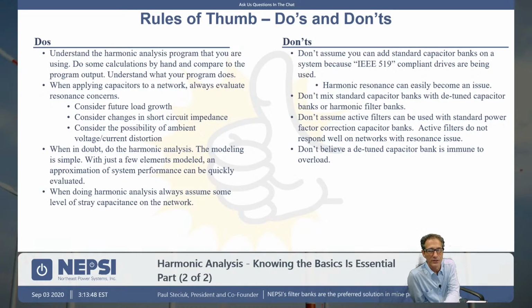Because that will teach you how to get around and how to analyze: what are the ohms, what's the current flow, is it in amps, is it in percent, is it VTHD, what is that value? It really pays to spend the time to dissect the program that you're using and really understand what the output is and what you're reading. You should be able to replicate it on paper, and once you can do that, you will definitely understand what you're doing.